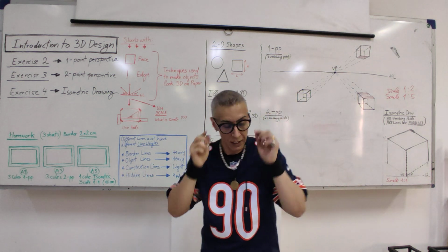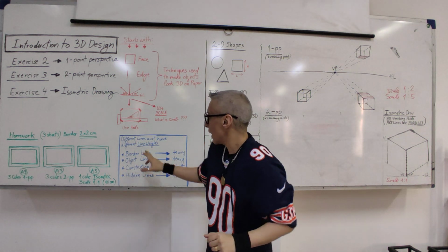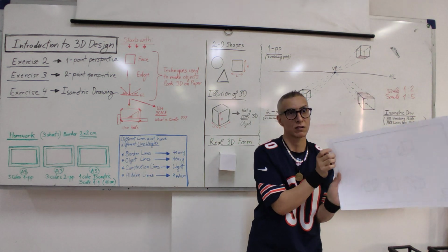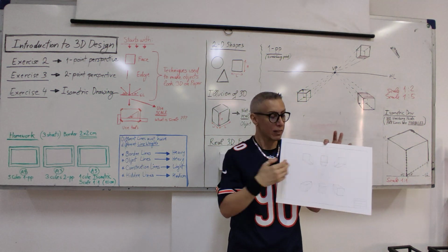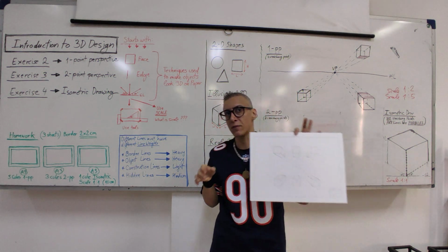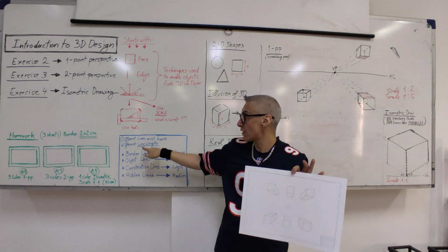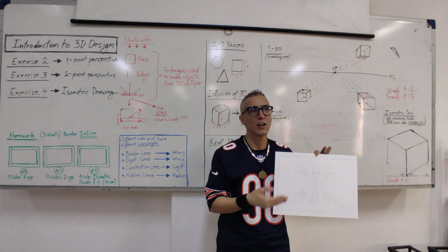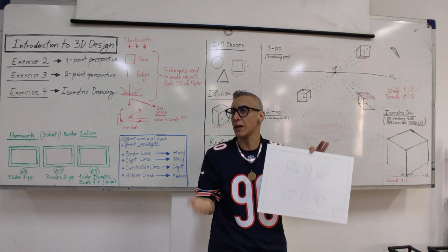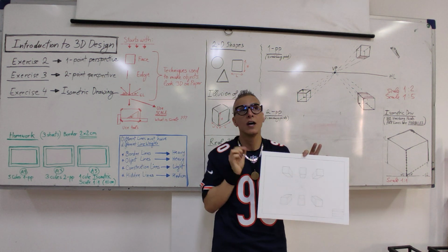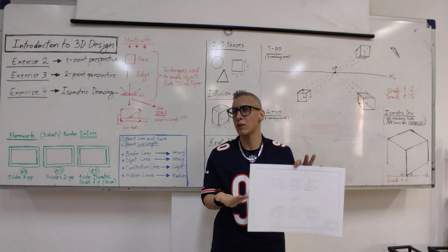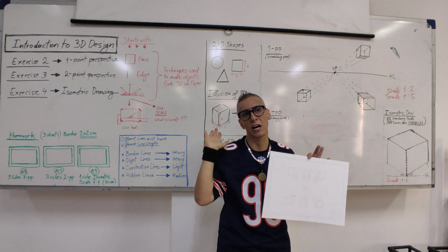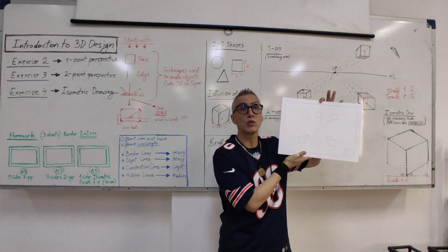Now, we have to be careful about certain things: the way you draw your drawing. The lines, you need to be very careful. Different lines must have different line weights. In design, later, you will see that there are many types of lines and many line weights, meaning the thickness of them. For our purpose, we are still at the beginning. We will use three different types: heavy, medium, and light. If you manage to do that, your work will look perfect.